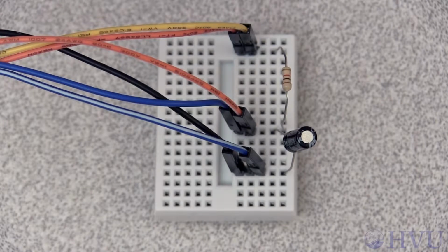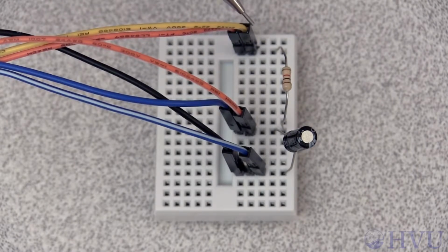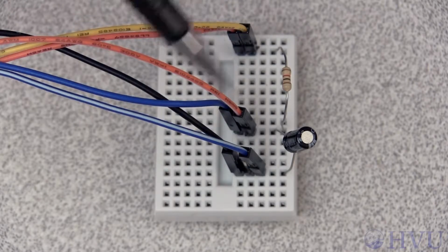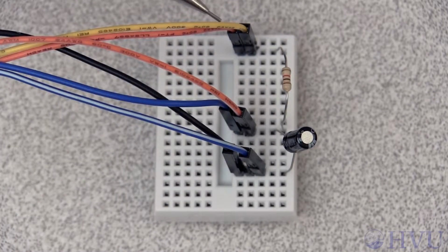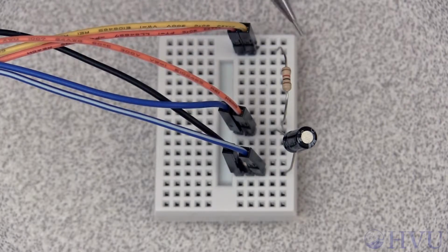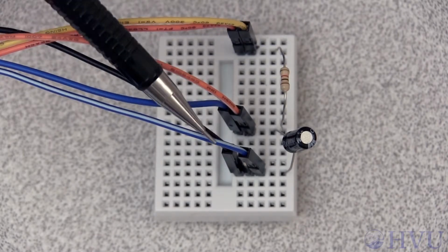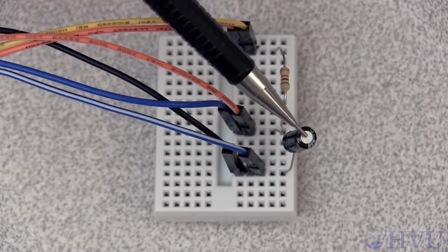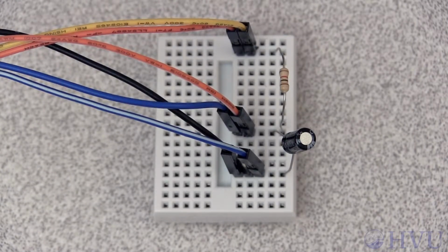This is our RC circuit. Channel 1 of the waveform generator, this yellow wire, is used to apply the input voltage. Ground is at this terminal down here. I'm using channel 1 of the scope, the orange wire and the orange wire with the white stripe, to measure the resistor voltage, and channel 2, the blue wire and the blue wire with a white stripe, to measure the capacitor voltage. Now let's apply power to the circuit and see how it works.